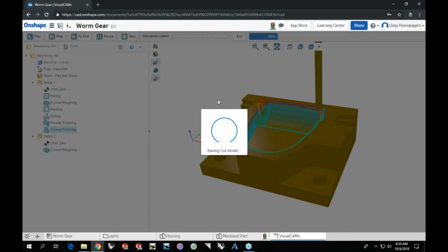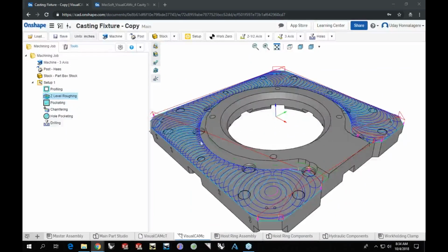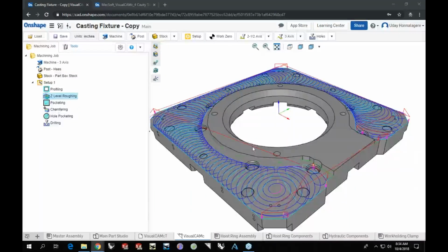Now, while we are waiting on that, I do want to quickly show you some of the types of toolpaths that you can generate on different classes of parts or complexity of models. So for example, here you're looking at a high-speed cut pattern toolpath that can be employed in a roughing operation, where you can generate very efficient toolpaths for roughing. It's generated by use of a constant tangential arc, which we can run at higher feed rates, and it basically prolongs your tool life and reduces wear.